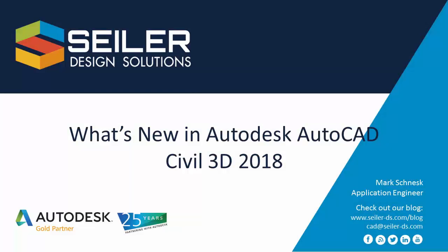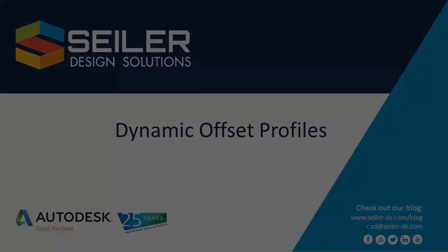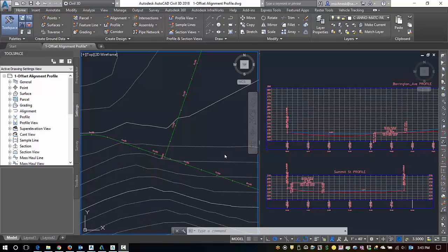What's new in Autodesk AutoCAD Civil 3D 2018? In this video, dynamic offset profiles. New in Civil 3D 2018 is the ability to create dynamic offset profiles. You can create dynamic offset profiles using the same commands that you use to create offset alignments. The profile geometry is offset using default cross slope, which you can modify by editing the profile properties.